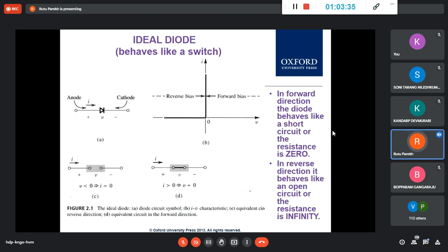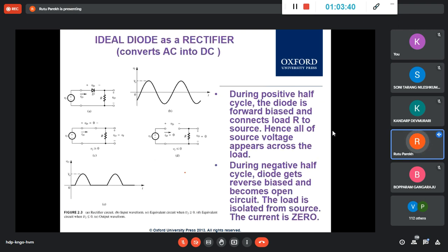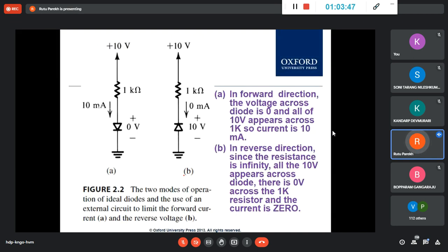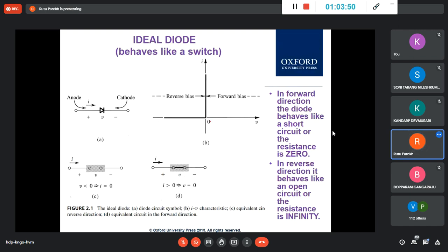For the diode, one is the ideal diode model, and the other is the linear model, which we will see. In the forward bias, you had a characteristic like this, and then like this, so this is a straight line. Forget this now, this is the practical thing. This is 0.7, 0.8 volt, and these currents are in milliamps.